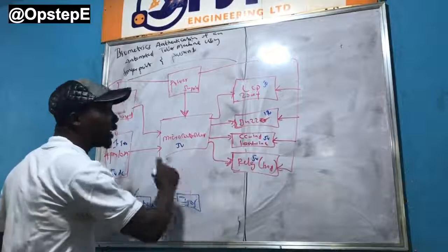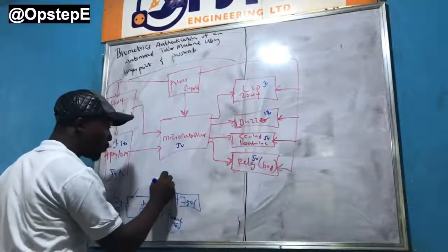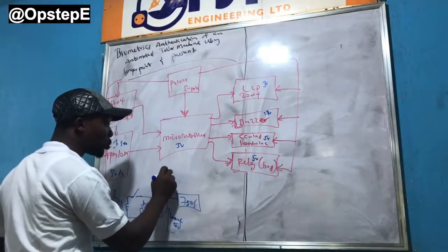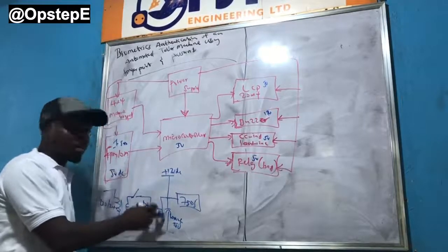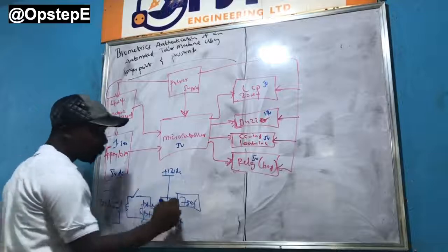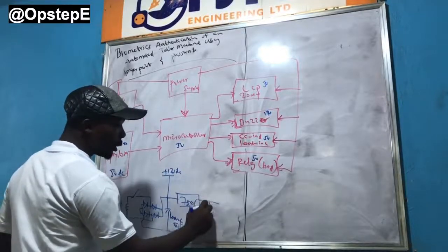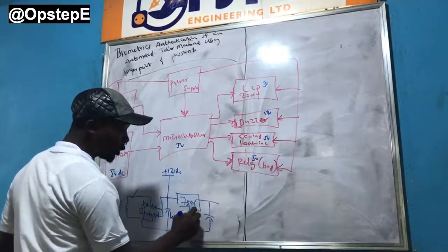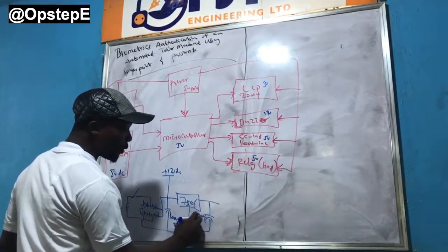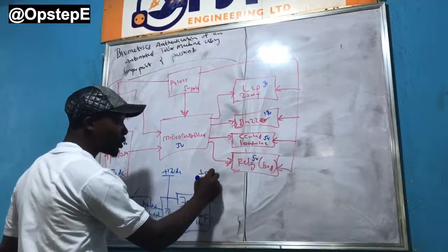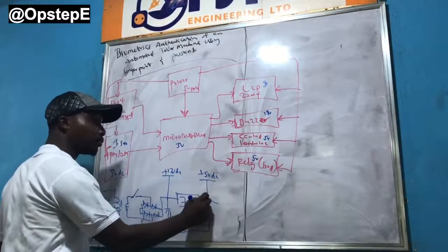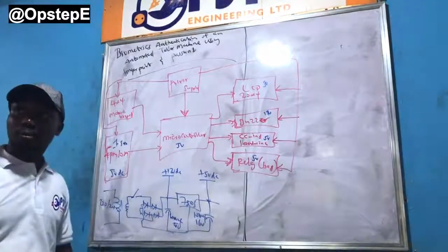Now, the component that requires 12 volts, which is the buzzer, will get the plus 12 volts this way. Alright? So the common, and then you have another capacitor here. This is usually 100 microfarad, 16 volts. And then the components that require plus 5 volts can get it here. Does it make sense?